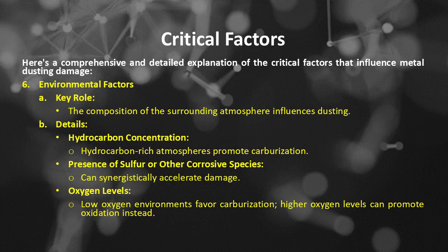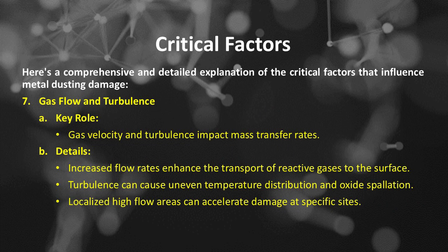Details are: hydrocarbon concentration. Hydrocarbon-rich atmospheres promote carburization. Presence of sulfur or other corrosive species can synergistically accelerate damage. Oxygen levels: low oxygen environments favor carburization. Higher oxygen levels can promote oxidation instead. Number 7 of the critical factors that influence metal dusting damage is gas flow and turbulence.